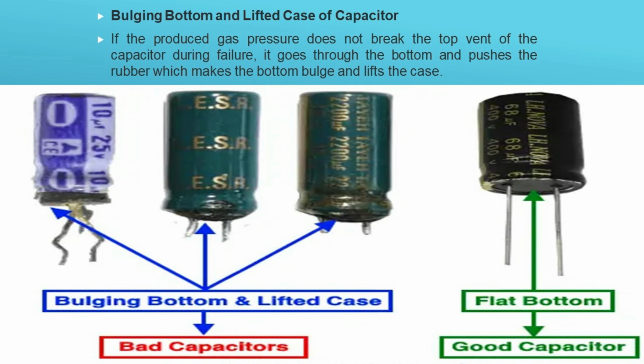Method 6. Test the capacitor by continuity test mode. In the DMM and analog meter, the continuity test mode can also be used to check whether the capacitor is good, open or short. To do so, follow the simple instructions below. Disconnect the power supply and remove the capacitor from the circuit board. Fully discharge the capacitor using a resistor. Rotate the knob and set the multimeter in continuity test mode.